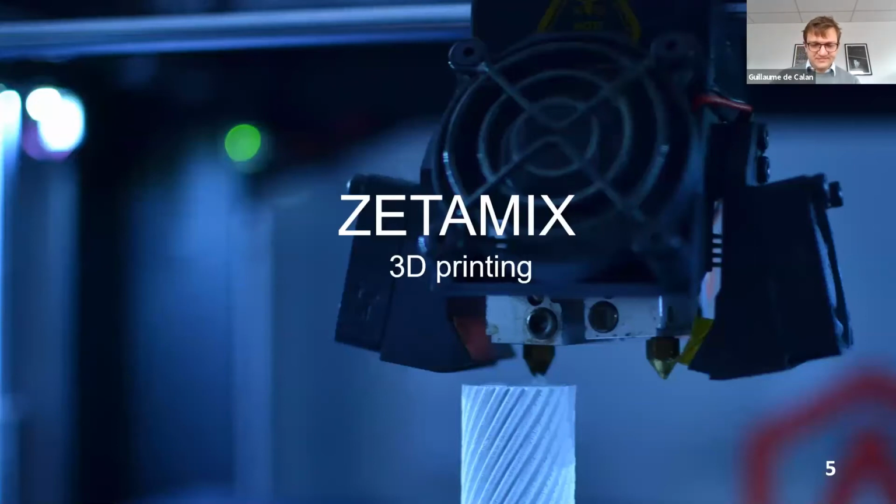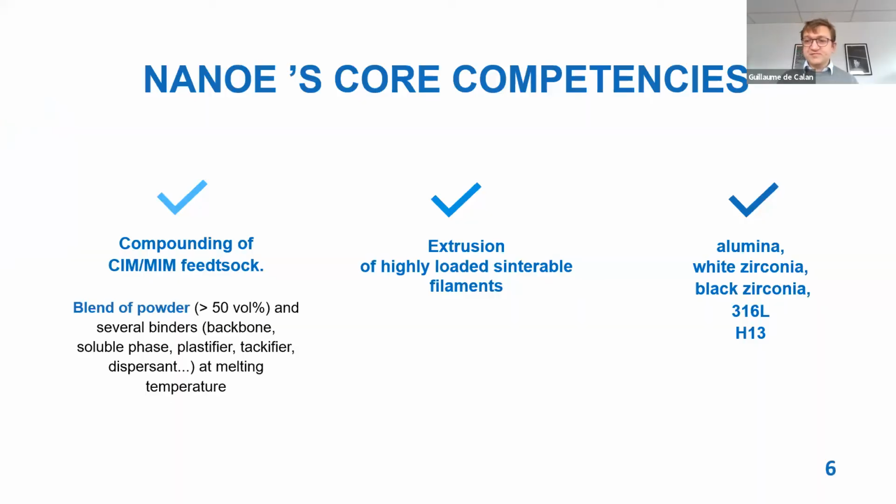Extrusion-based process, let's say. So we've been using what NanoE does best, which is preparing raw materials. And in this case, we've started from what we call ceramic injection molding and metal injection molding feedstocks. I'll go back to that later on, so I'm not going to go too much in detail. And these feedstocks, which are a mix of plastic binder and powder, we extrude them into a filament. And that's really the two key points. The compounding and extrusion is what will allow us to make a material compatible for 3D printing.